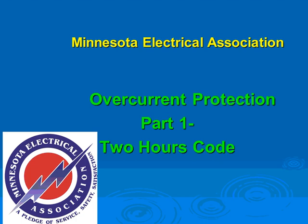When we do maintenance on electrical equipment, I always say the safety of the electrical power system starts with installing safe equipment. So how do you make sure that this 4,000 amp switchgear, with an 85,000 amp interrupting withstand rating, is really going to interrupt an 85,000 amp short circuit? How do you know that what's written on this piece of equipment is how the equipment is going to act? Well, I don't know.